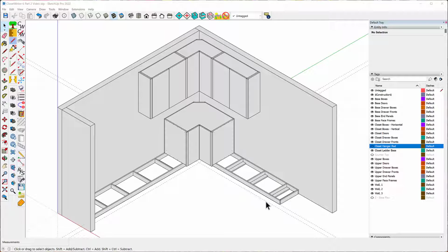I could have moved this line back about 13/16 to make it all line up with cabinets, but I needed the actual 24 inches in order to hang the clothes that were in the closet. I needed a width of 24 inches. So what I did to compensate was I made my cabinets, I think I made it 13/16 inches deeper than usual on the base. So that was our setup.